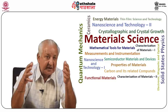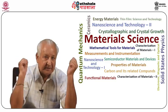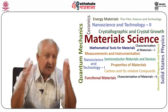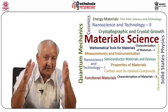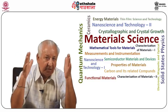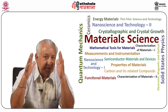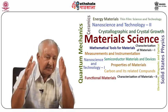The following steps describe the process as illustrated in figure 30.7. The material to be grown and the encapsulant are placed in the crucible, which is heated by an RF field. The encapsulant melts first, and a layer of encapsulant separates the melt from the crucible as illustrated in figure 30.7a. The seed crystal is brought to the melt surface as shown in figure 30.7b.